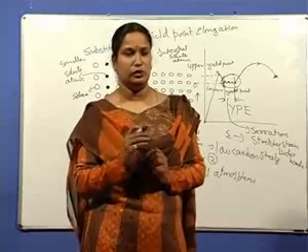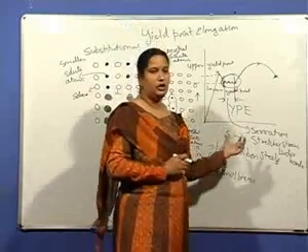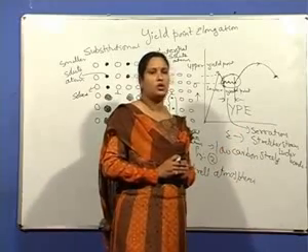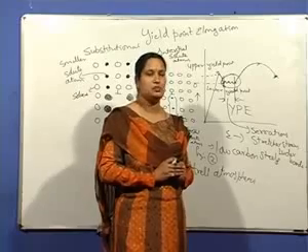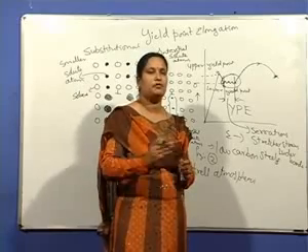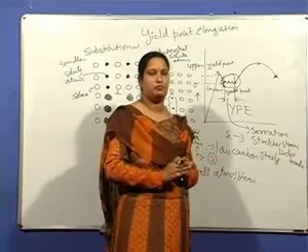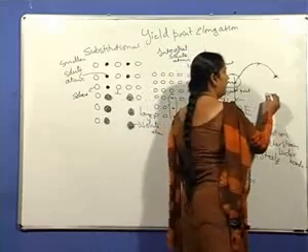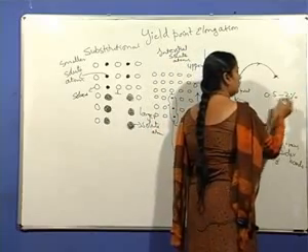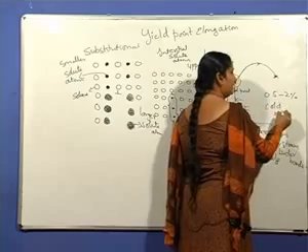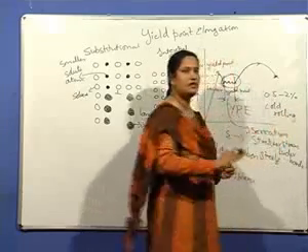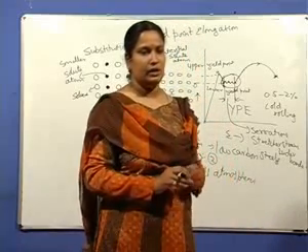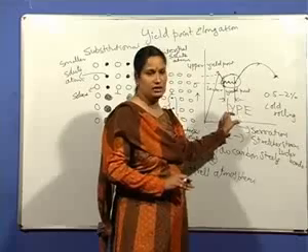In order to overcome this defect, in order to prevent this yield point elongation, a very small cold rolling is given just before sheet forming. A small cold reduction of about 0.5 to 2% cold rolling is given to these low carbon steel sheet materials in order to prevent this yield point elongation.